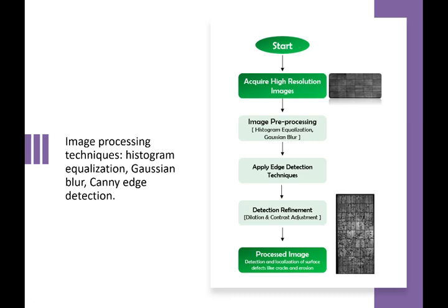The second part is to analyze the exact corrosion and cracks on the surface of the solar plate, because, as mentioned, due to cleaning of the solar panels and the density of the dust and silica particles inside the dust, they create more scratches on the surface of the solar panel. That also reduces the efficiency.